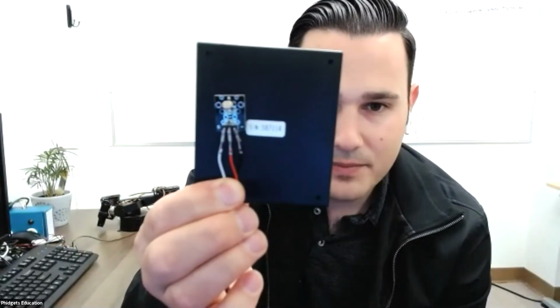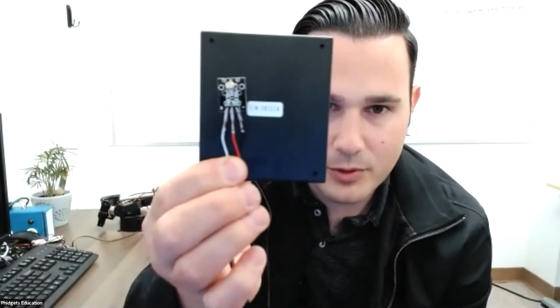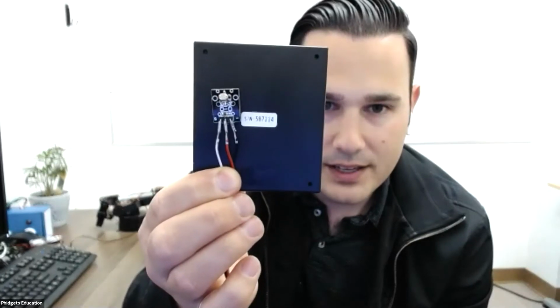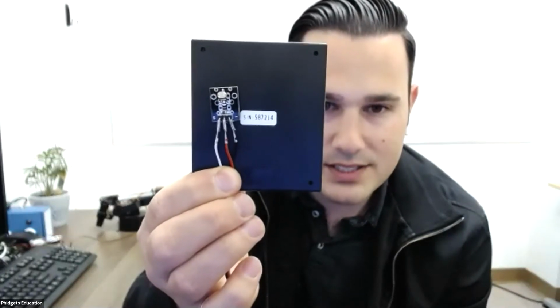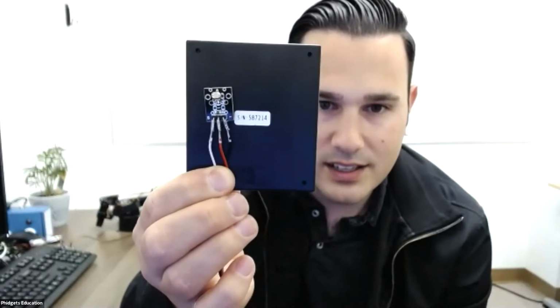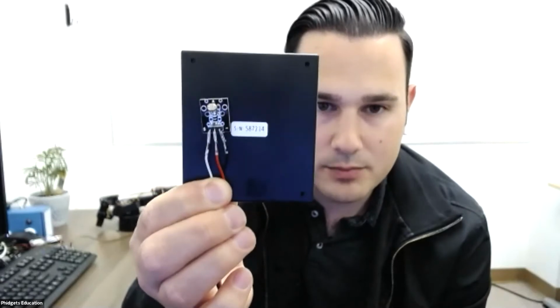But basically what I'm going to do then is take this device and my wires. I'm going to find the signal and put the white wire there, find ground and put the black wire, and then put the red wire on power. So I now have this set up here. It looks something like that. It's going to be hard to focus on that, but there we go. So I have my wires now connected. You can see the S is white, the black is on negative, and red is positive.